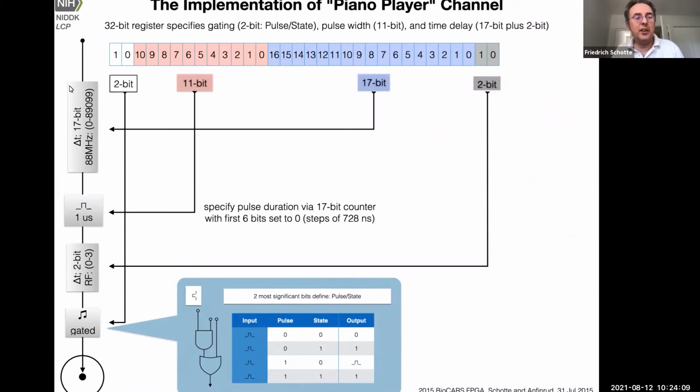And it consists of a variable delay, a pulse generator, and a high resolution relay that is optional, and some gating. So you can operate it in 2 modes. You can just by software control turn it on and off. So you can have like a falling or rising edge every millisecond, or you can generate pulses with precisely timed edges, say exactly 486 microseconds and 243 nanoseconds after the 1 millisecond clock cycle, you want to fire it. You program this delay. And then you want to give it a pulse duration of exactly 1 microsecond. You program this delay here.